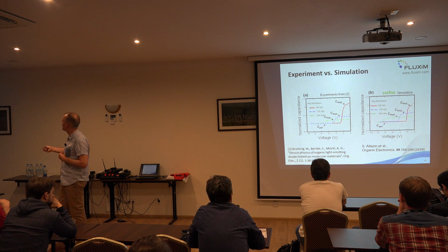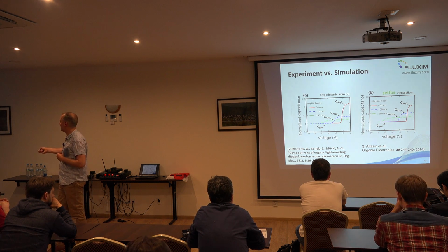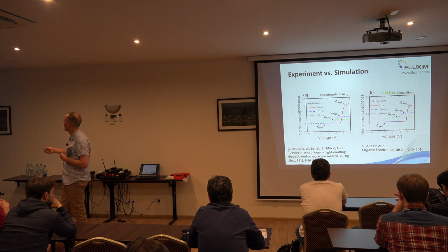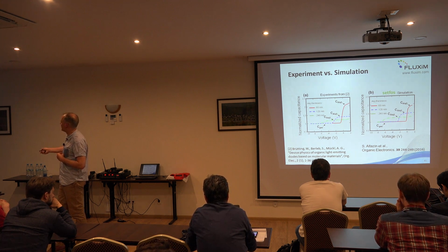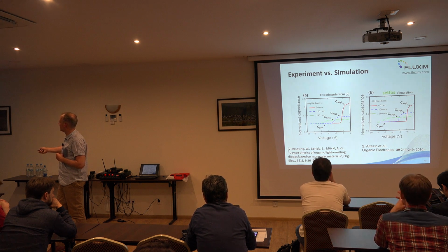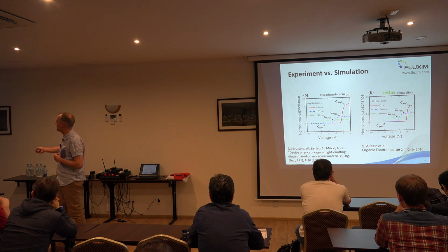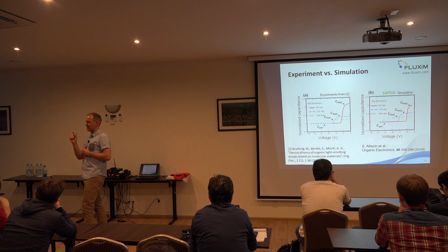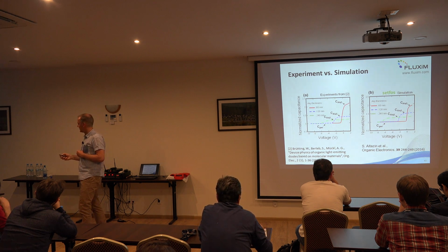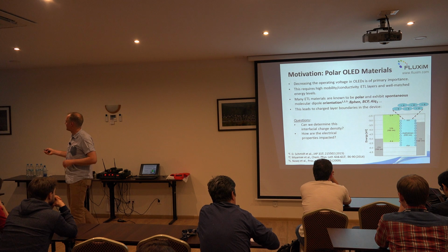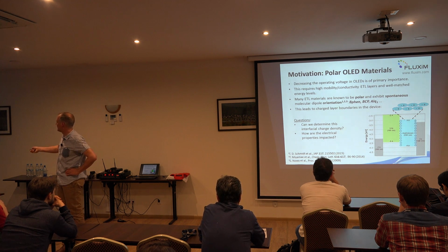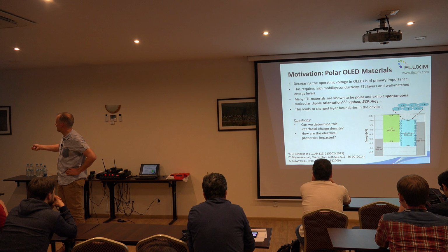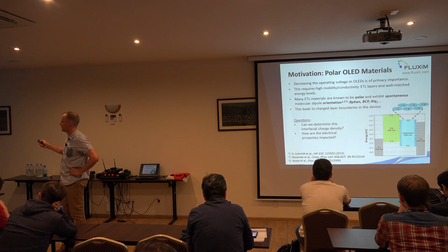So that's qualitatively the explanation here. I'll show some sketches as well. But already here we see that the simulation can nicely reproduce the scaling of this signal with thickness of Alq3. Let's look at the blue dashed line. For this thickness, 120 nanometers of Alq3, this level of capacitance corresponds to the capacitance of the Alq3 layer. What we have observed is that the holes will already enter the device and pile up at the interface. Because we have so many free holes that pile up, they will define a capacitance across the Alq3.